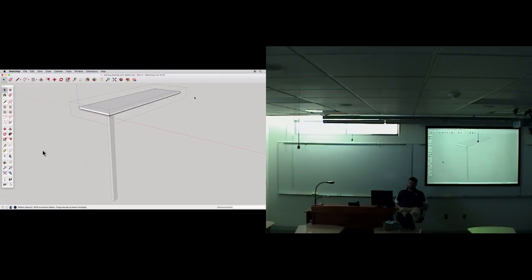Use the Select tool and double-click on the tabletop. The bounding box changes, indicating that we are now editing the group. Still with the Select tool, click outside of the dotted surrounding box to close the group. Practice this a few times with our group and component.